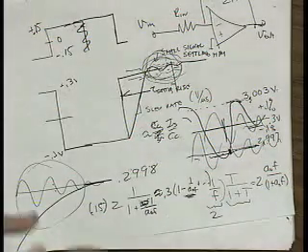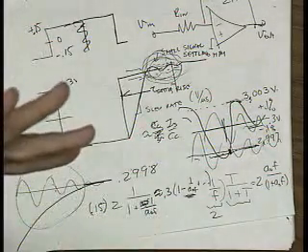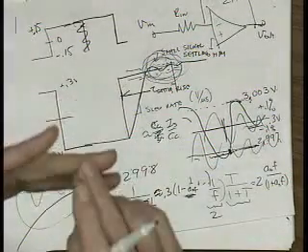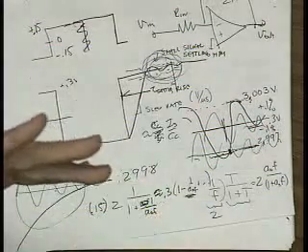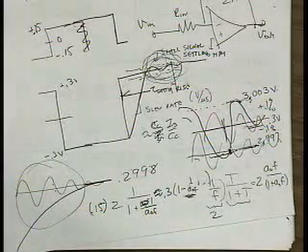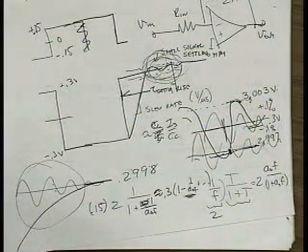So there are three things: slew rate; small signal settling, which gets slower as you ask for more gain; and static settling, which gets better as you ask for more gain. So you see things are sort of fighting each other here a little bit. But that's pretty classic.